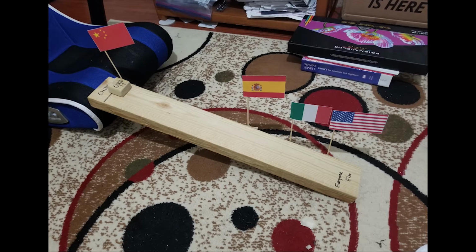One potential source of error is not calculating the correct amount of time it took for the wood to reach the bottom, because I don't have a high-speed camera, I only have my cell phone, and it's sometimes hard to see when it reaches the bottom when it's a blurry mess. Another source of error is me not sanding down the wood perfectly flat. There might have been some micro bumps I couldn't see, but I think I did pretty good with what I had. Finally, the Sharpie I used to write the letters on the ramp itself might have affected the coefficient of friction of the surface.